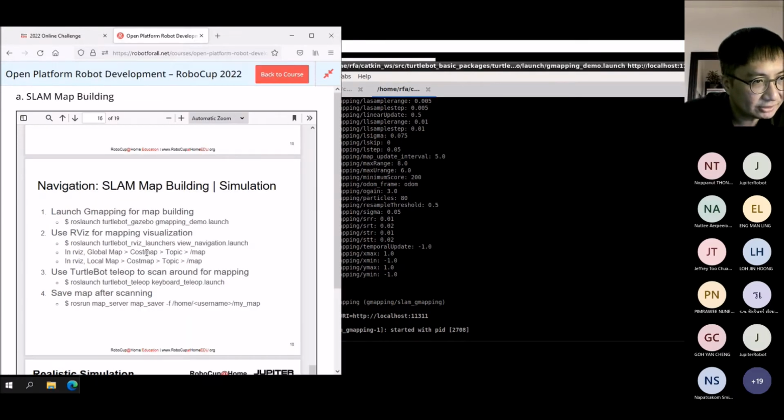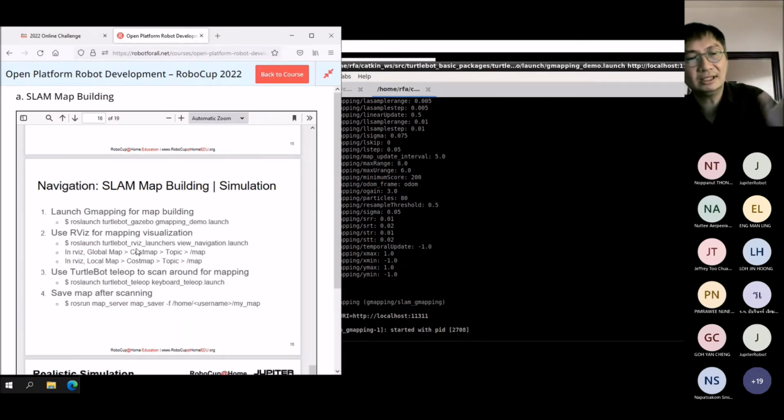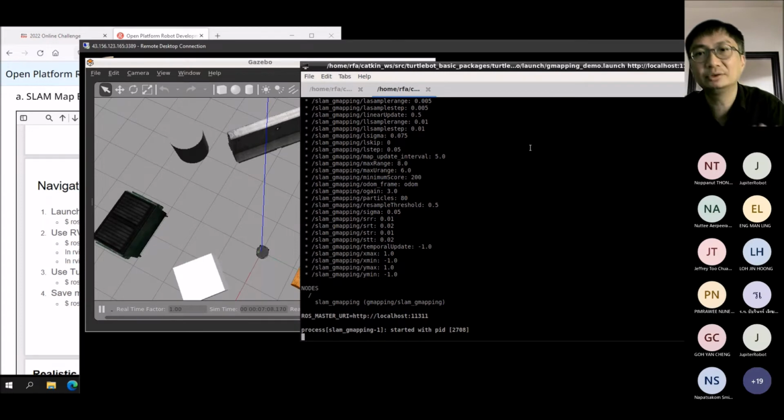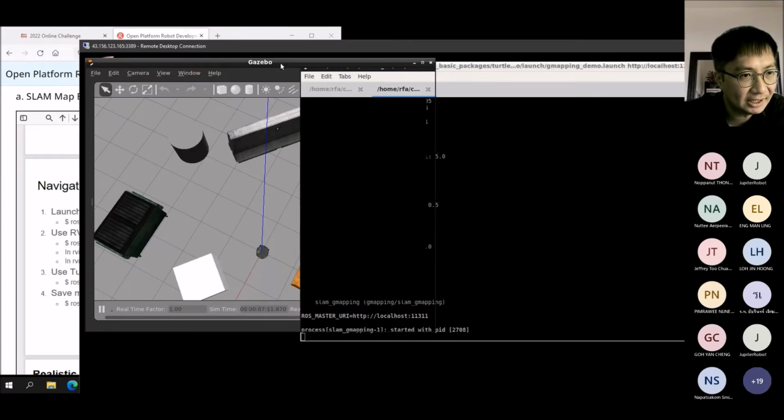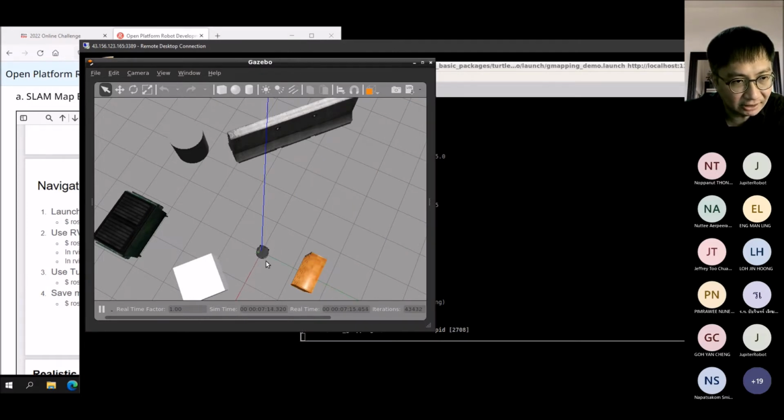So the third step is to run the RViz. Why we need to do this is because we want to see the sensor data. Just now I explained you have the TurtleBot and the RGBD sensor, but over here we are taking the laser scan. So we have a package in ROS that converts the sensor data, the RGBD data, into the laser scan.